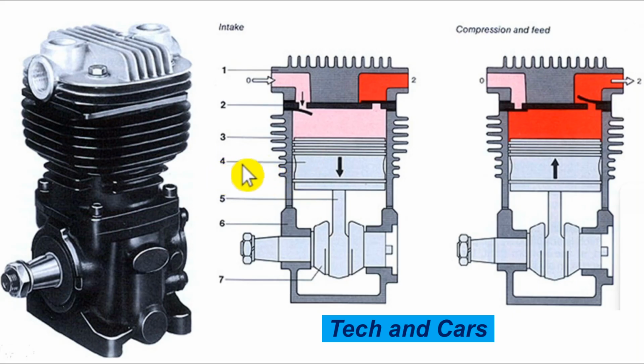So always make sure that the pneumatic brake system is fully drained, and make sure that fresh air that is coming to the air compressor is clean as well.